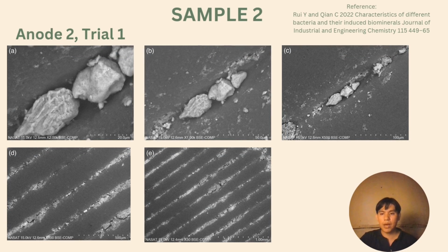It has a smooth surface with line patterns, but this contains larger and more accumulated particles compared to anode 6. So figure C reveals particle alignment within cracks, indicating advanced fragmentation. Whiter areas suggest rust, while parallel lines hint at erosion, reducing surface area and structural integrity. Significant degradation in current conduction and electrochemical stability risks potential future failure.